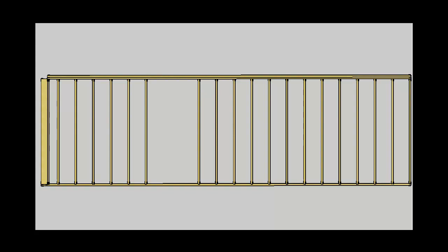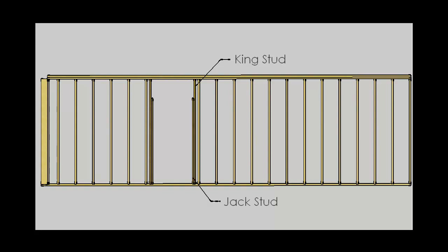So, in a load-bearing wall, when elements such as doors and windows are introduced, challenges of load transfer have to be addressed. In order to create an opening in a wall, we have to remove studs. And remember, on a load-bearing wall, the studs are transferring the upper loads down to the foundation. When we remove those, that creates a weak spot in the wall. This void is compensated through the framework of the new opening. In this case, we start with a doorway.